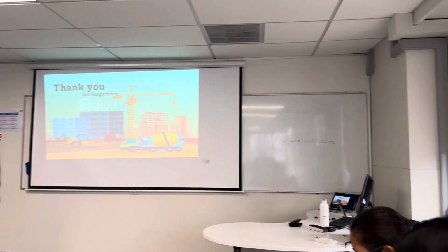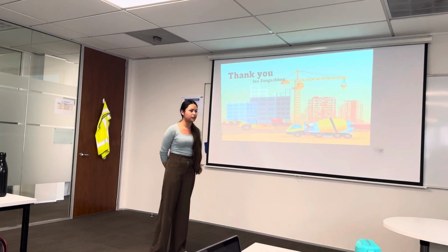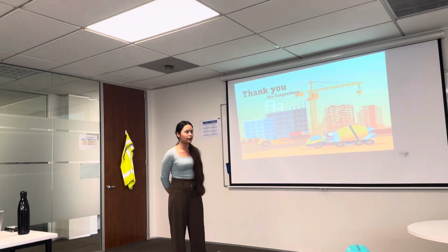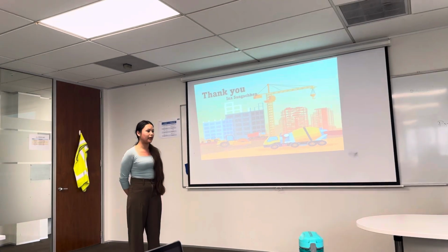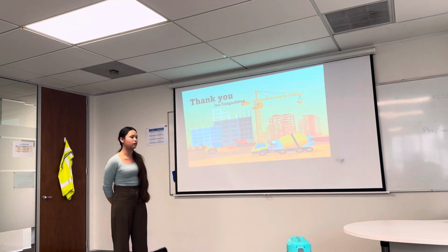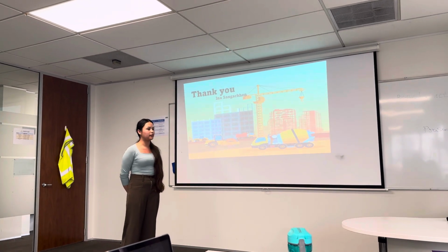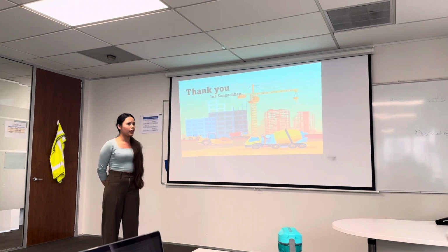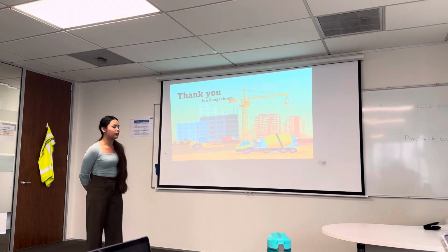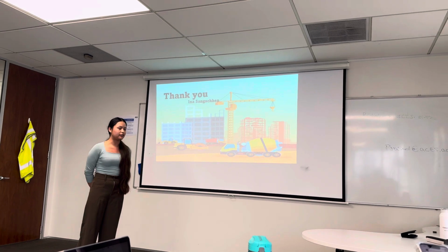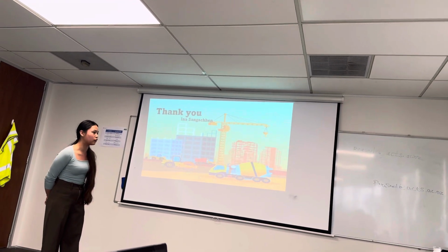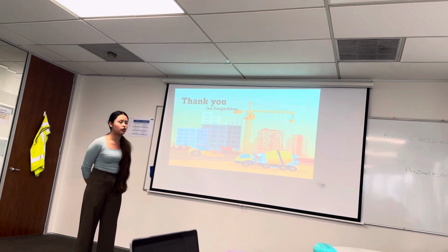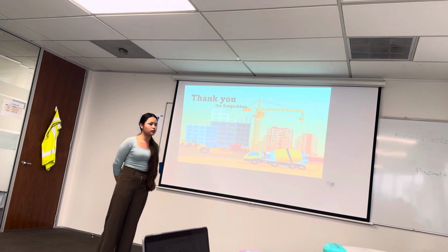How do you take off reinforcement? Okay, reinforcement. Reinforcement has different diameters. So to take off the reinforcement, first we calculate as per the drawing, as we see in the drawing, and we find out its length. The length is in mm, we convert it into kg, and after that we convert it into ton. So it gives the overall quantity of the reinforcement required for the construction project.